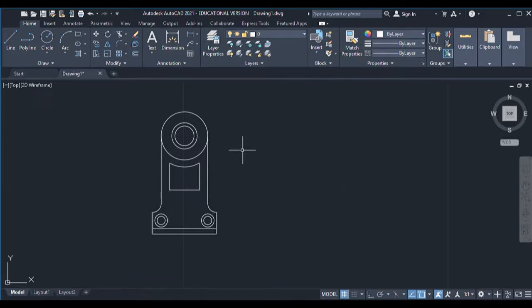This is a complete drawing that we are making today using AutoCAD. Okay, so look at how beautiful it is once I put up the dimensions around this object. We have this dimension here or there, so you can choose whichever you want to use. I will click dimension, and then you can use any from here. I will use linear for a start. You click linear, and then you click where you want it to start from. I'll click that point and the other point, and then I'll stretch like this.